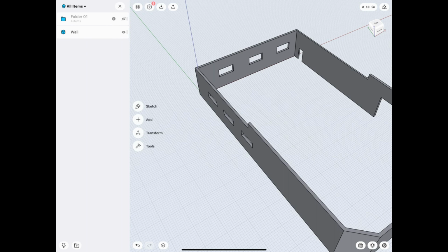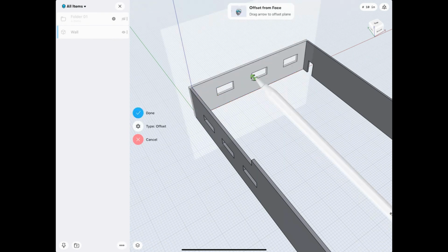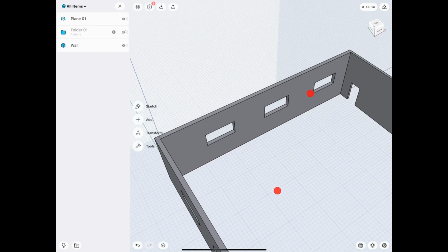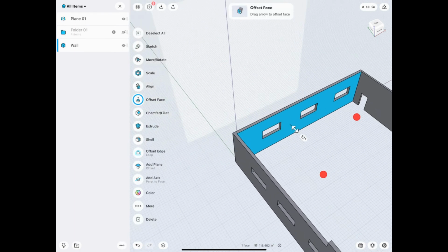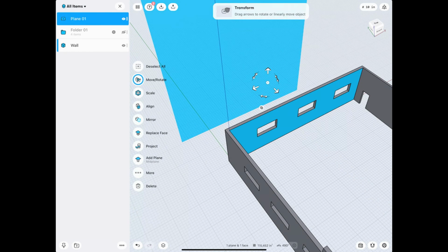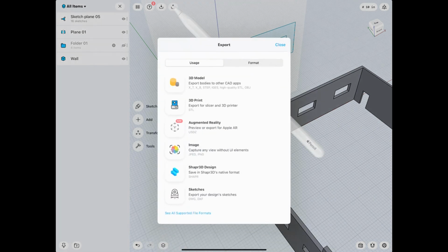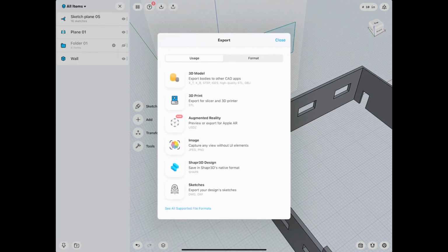Another really nice thing about this program is I could go to construction plane, select this plane, make myself a construction, and then check this out. So I select this face and select this construction plane and project myself an elevation view onto it. So in this elevation view now I could add dimensions or export for AutoCAD or something, because we have export sketches as DWG or DXF.